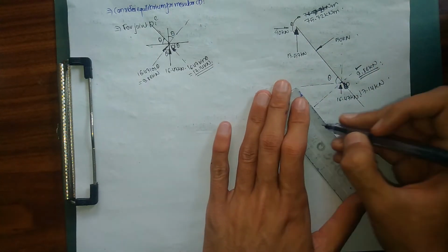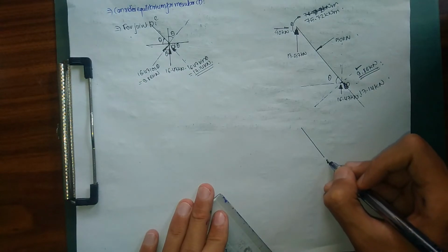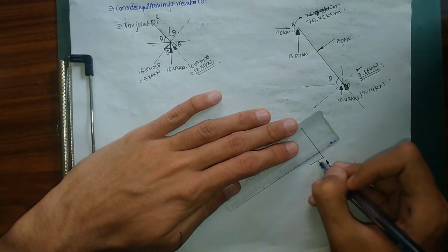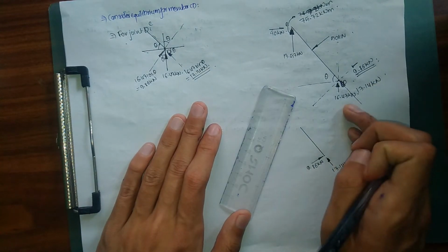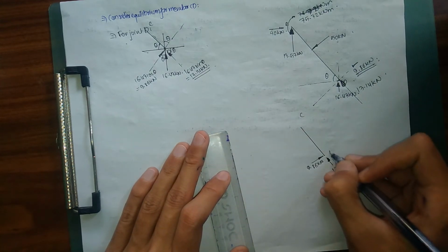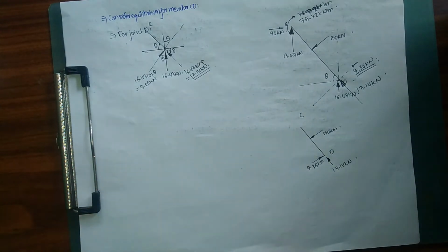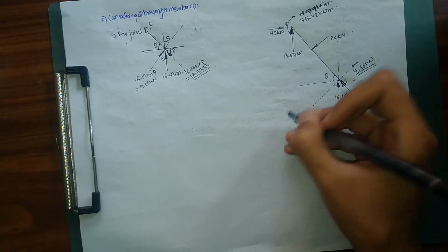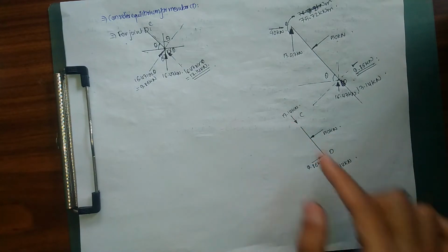This figure is a little bit messy, so let me draw my figure this way. After resolving my 16.43 kilonewton, I get 13.14 kilonewton over here, and next I get 9.86 over here. So this is my member, this is my joint D, and somewhere in the middle I have 50 kilonewton. As I already explained before, in order to maintain equilibrium for my joint C along this axial direction, another force of 13.14 kilonewton must act in this way. So I can put another force over here.